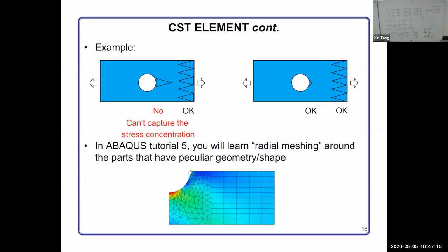You can also, because this is a symmetric problem, around the x direction, this part and this part are symmetric. Around the y direction, this part and this part are also symmetric. So if you calculate only a quarter of this plate, you can capture all the essential mechanical characteristics.